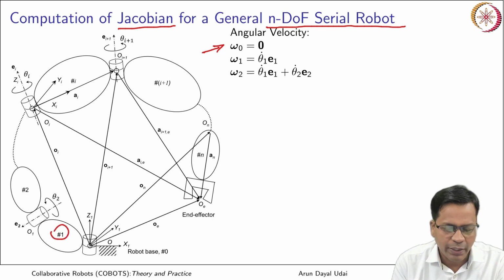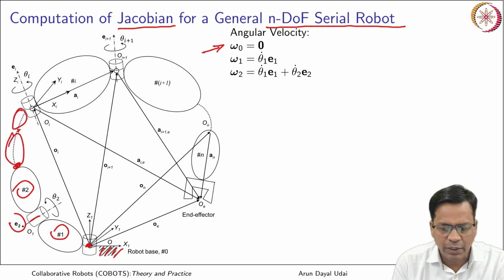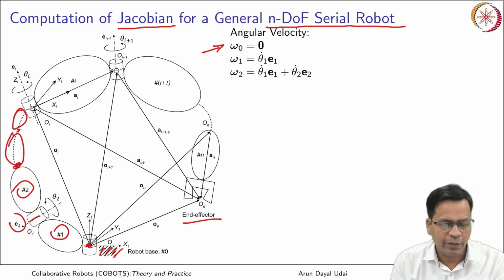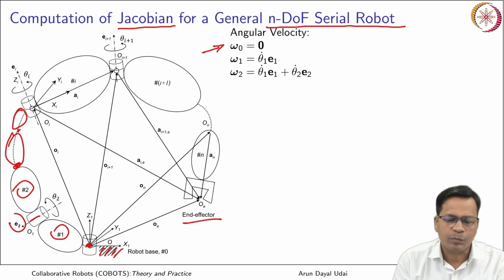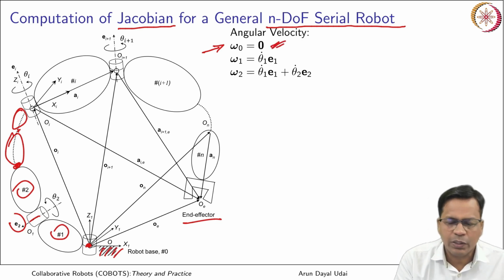This is link 1 attached to the frame 1 and it is attached to the ground. This is next link, okay. This is the next velocity, angular velocity at the joint, next joint, next link, next joint, next link, and so forth till it terminates at the end effector, which is here, okay. So omega 0, because it is attached to the ground, is equal to 0.